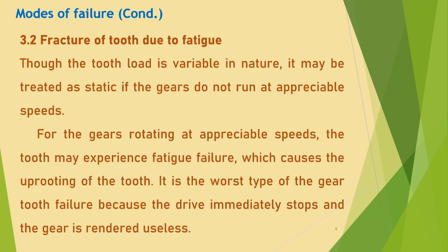The second mode of failure to be considered is fatigue of the tooth. Though the tooth load is variable in nature, it may be treated as static if the gears do not run at appreciable speeds. For the gears rotating at appreciable speeds, the tooth may experience fatigue failure, which causes the uprooting of the tooth. It is the worst type of gear tooth failure because the drive immediately stops and the gear is rendered useless.